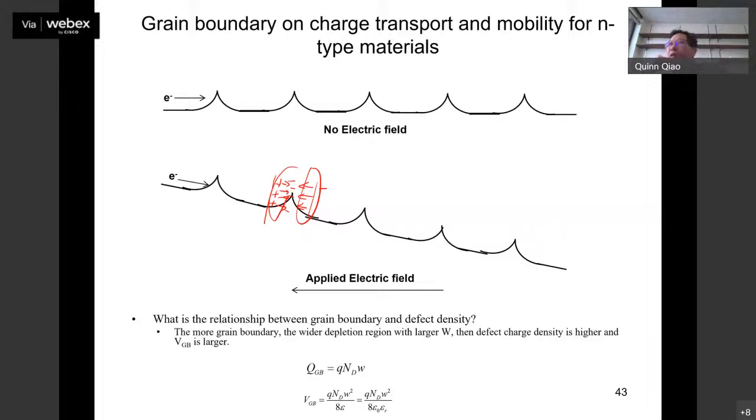Perpendicular, you mean not across the PN junction, right? It's parallel, and then the electric field doesn't affect you. So still the transport is through the diffusion, right? Is it the diffusion or the drifting? Only when your electric field will not sweep everything away will you be able to see this kind of slow process. Otherwise, you cannot see it.